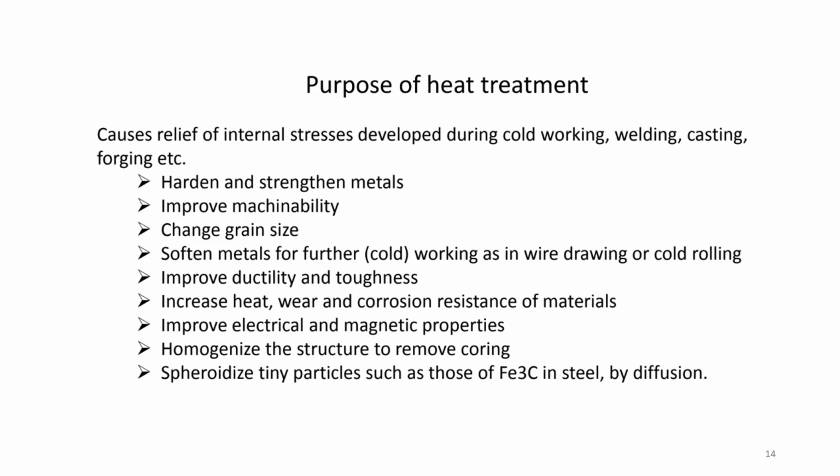It causes relief of internal stresses developed during cold working, welding and casting, forging, etc. It hardens and strengthens metal, it improves machinability, and it changes grain size. It can soften metals for further cold working, as in case of wire drawing and cold rolling.